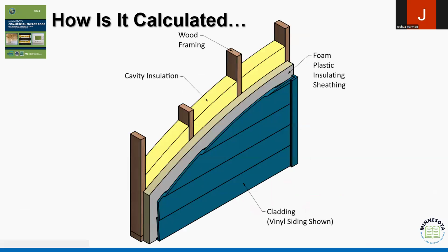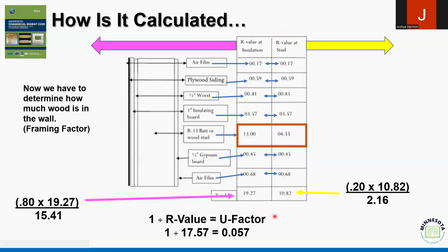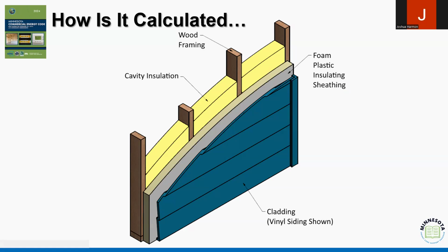But what we do when we calculate a U factor, and the purpose of the COMCheck, is to look at the entire wall or an entire assembly and say, okay, how many 2x4s? How much insulation? How many windows? How many doors? Right? And then we do that total math calculation. So instead of having to do this type of evaluation every time, we do COMCheck to do that quick math calculation. Right? That's the point of COMCheck, or ResCheck if you're looking at it in residential terms.